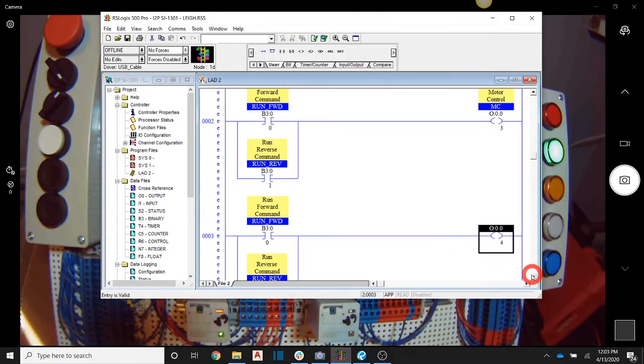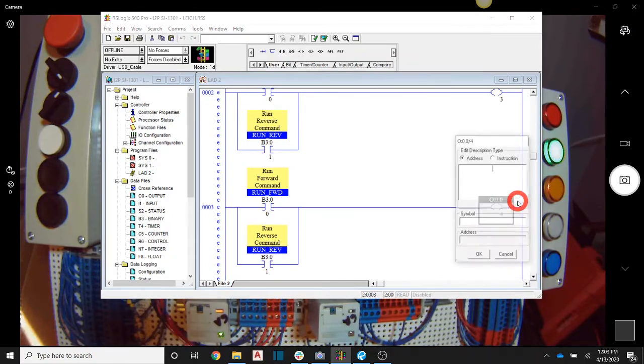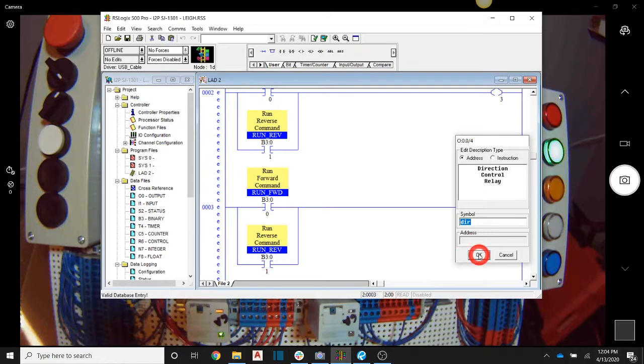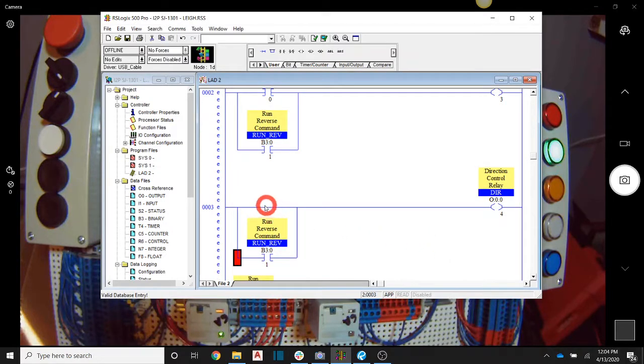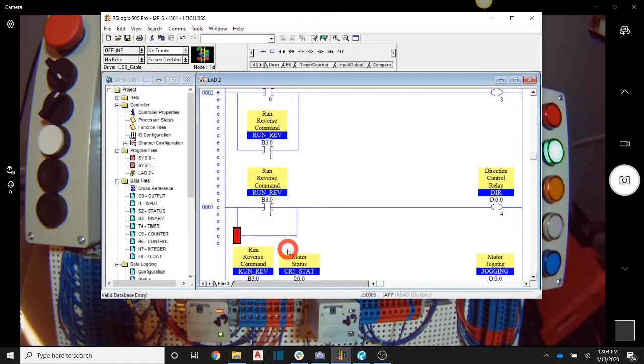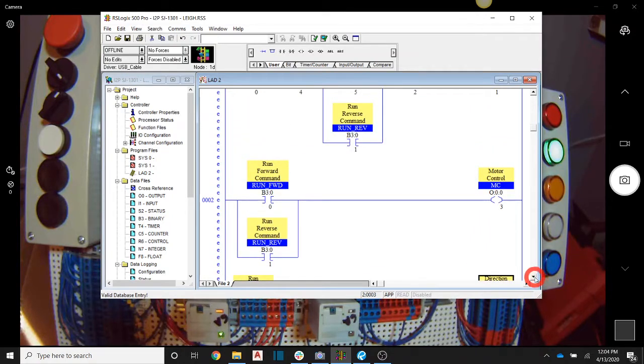And so this address is control relay 2, which is our direction control relay, which on the job sheet I call DIR. So for DIR, I only want that one to come on when I tell it to run in reverse. So I have those two outputs set up.